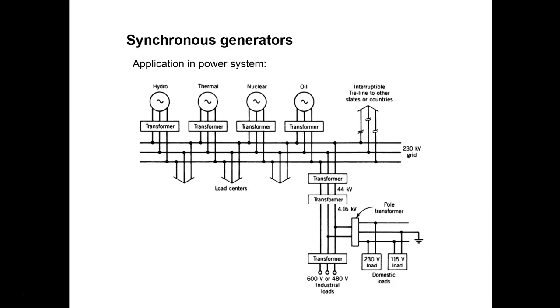For example, if we connect a synchronous generator to an infinite bus, then if we vary the mechanical power of the prime mover of the synchronous generator, the steady state frequency, hence the speed of the generator, will remain the same as the bus frequency. We will look at this in detail later on. In fact, in all the examples as well as questions in the exam and in the test for this course, the synchronous generator or motor is always assumed to be connected to the infinite bus.